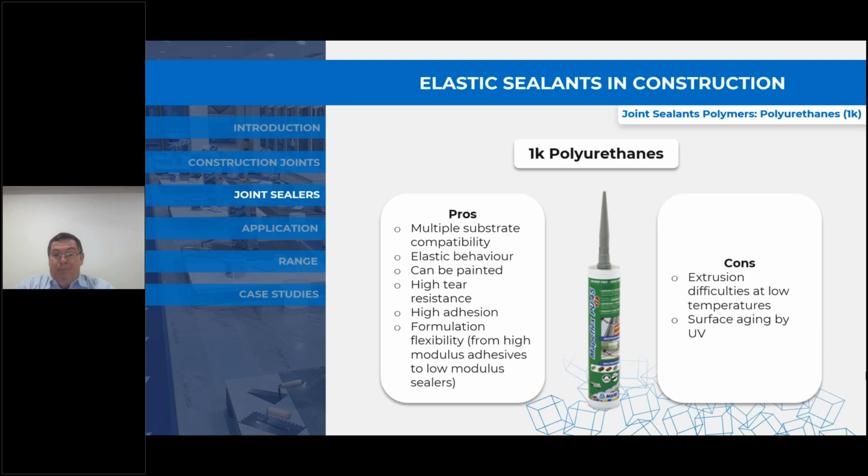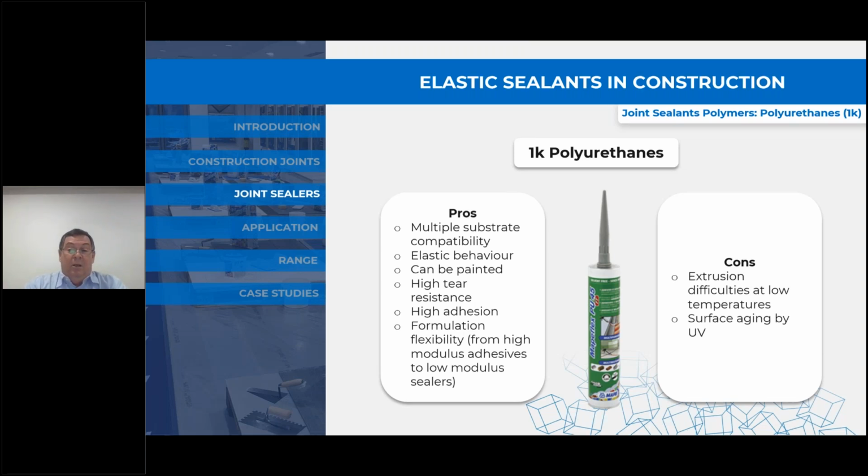And the cons, I guess, are the extrusion difficulties at low temperatures. They tend to be a little harder to gun than silicones. The surface aging by UV over time. They tend to get oxidation and crazing on the surface when exposed to UV.